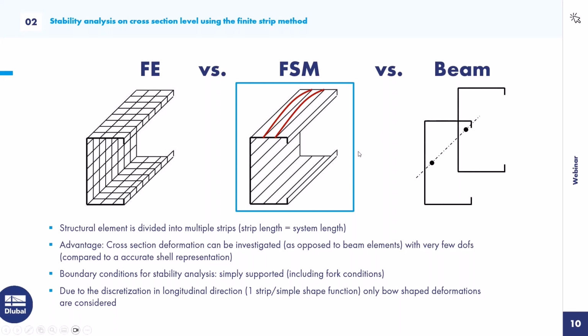And when we activate the finite strip method in the edit section dialog, a lot of these FSM members are generated, and the eigenvalue analysis is performed, and the eigen shape is stored, and also the critical bifurcation load is stored. And this happens on the go. So if we click it in the edit section dialog, it's done, and it finishes for like 50 analyses within less than 1 second. So this is quite a nice advantage of this analysis method.